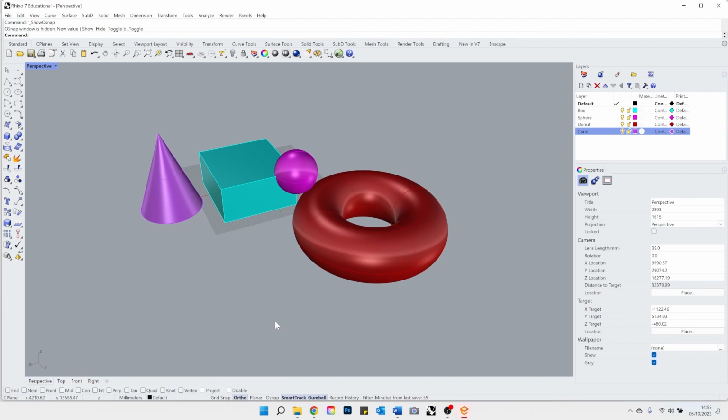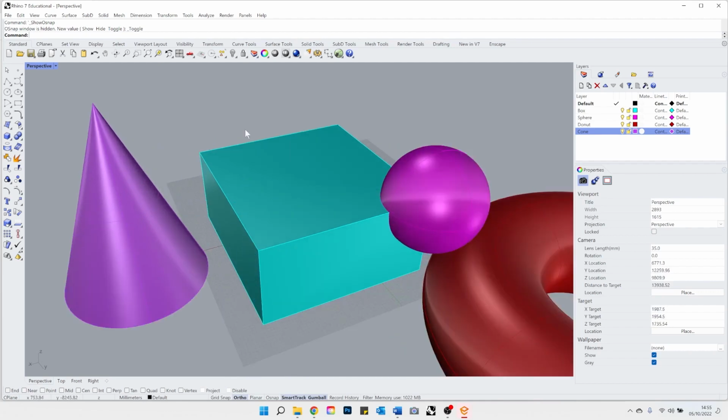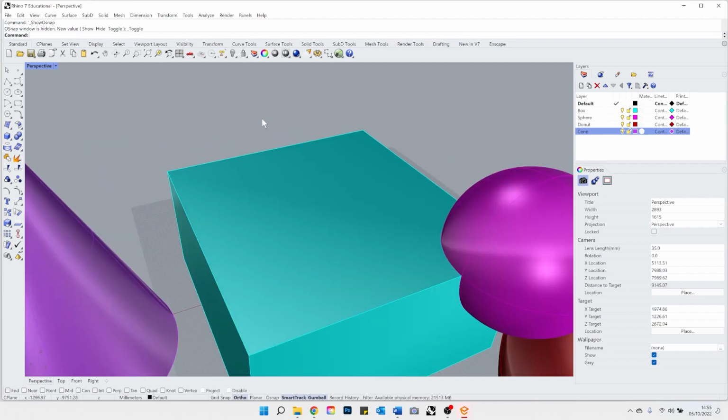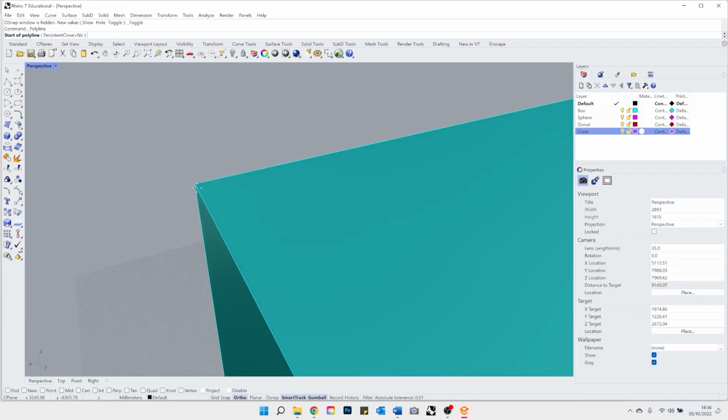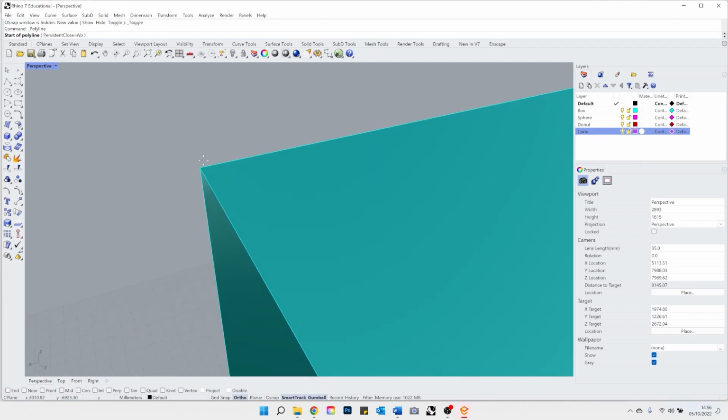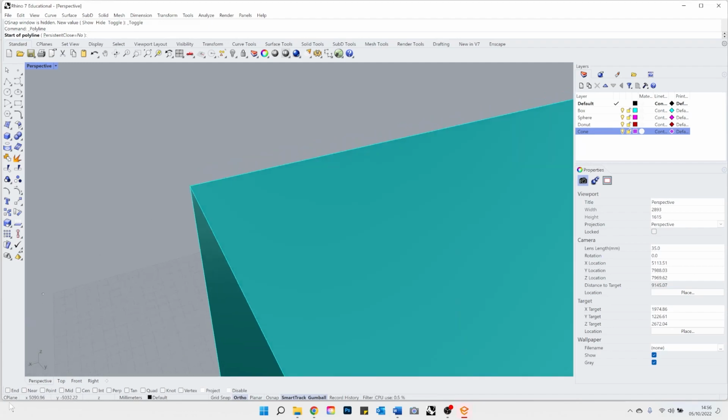So the idea behind those tools, those commands: if you need to draw something, if it's a 2D floor plan or a 3D object, and in architecture school we're always trying to be as accurate as we can. For example, if you need to start one object, or one curve, from the corner of a room, it doesn't matter how close you zoom in, if you don't have your snaps on, you're not going to be as accurate. You're always going to have this slight annoying gap in between. So your snap tools will help you to literally snap to an object.